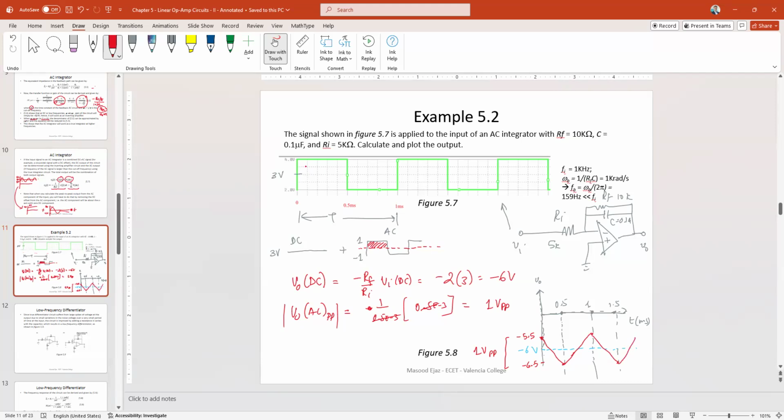If the first one is going to be the negative value of the square waveform, then it's going to start increasing. So if you want to start from this point, at 0.5 millisecond, then of course it's going to increase first because you have a negative value. So your slope is going to be positive because of this negative sign that you had.